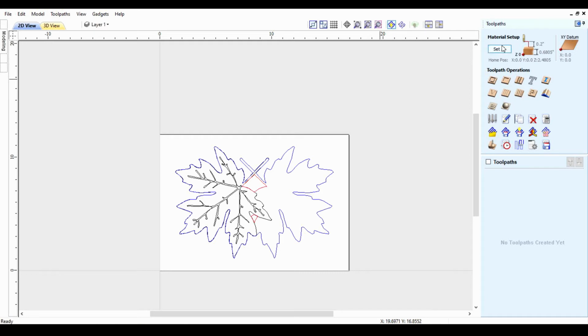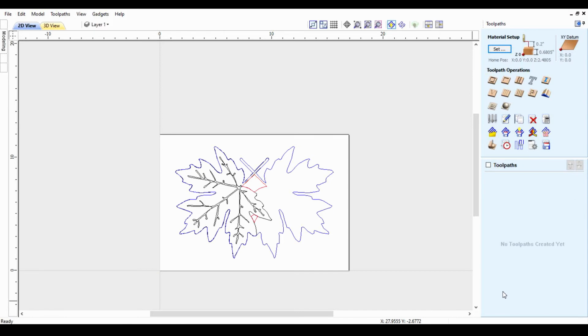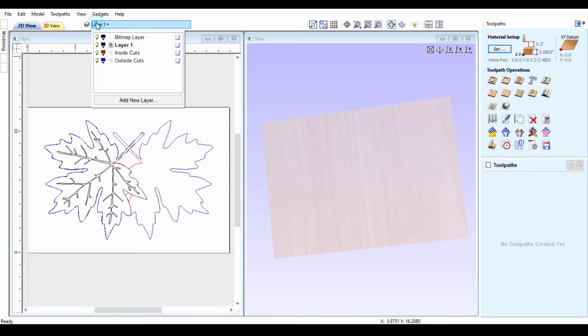Let's set the toolpaths. Let me set my thickness to my Z. If you hit Z and hit equals, bottom left corner, I'm going to make the gap above it pretty shallow, so we'll just pick 0.01, so if there's unevenness in the board, it'll still machine it off. Let me bring up both of these views here, side by side.